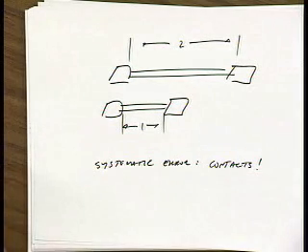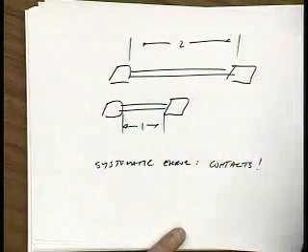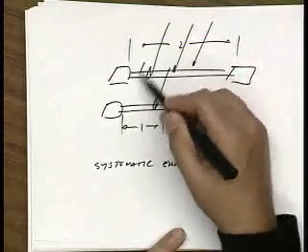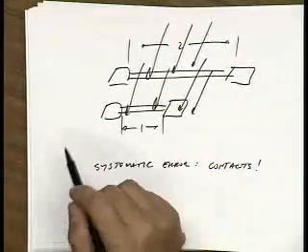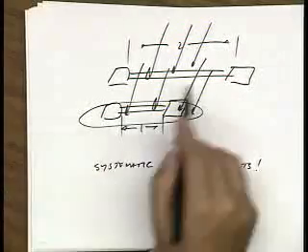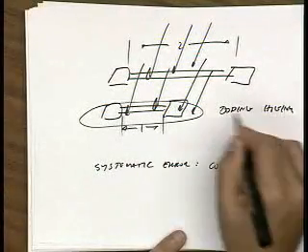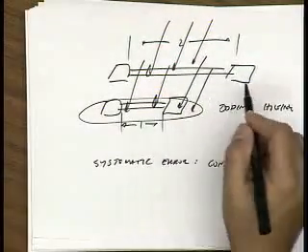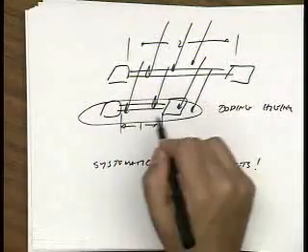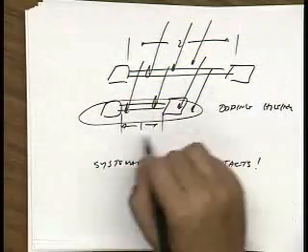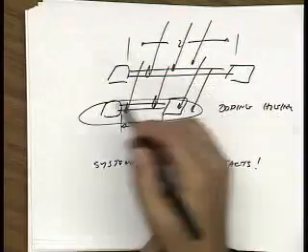Yes? You have gradient from left to right. That's right. So the way to imagine this is picture the doping coming in a particular direction, the dopants. So let's say the dopants are coming in this direction, and let's say that the doping is higher here than here. So this has a lower resistance than this one. So then you're not going to get a 2 to 1 ratio, not just because of the contacts, but because the doping is varied.